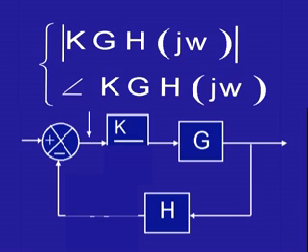The only thing is, in normal operation, the input here is a DC voltage. It may be changing, but it is unidirectional. The output of the tacho generator voltage is also going to be a DC voltage. But under test conditions, you are applying an AC voltage, maybe of a small amplitude here, and measuring an AC voltage of another amplitude here. So, this test can actually be experimentally performed.